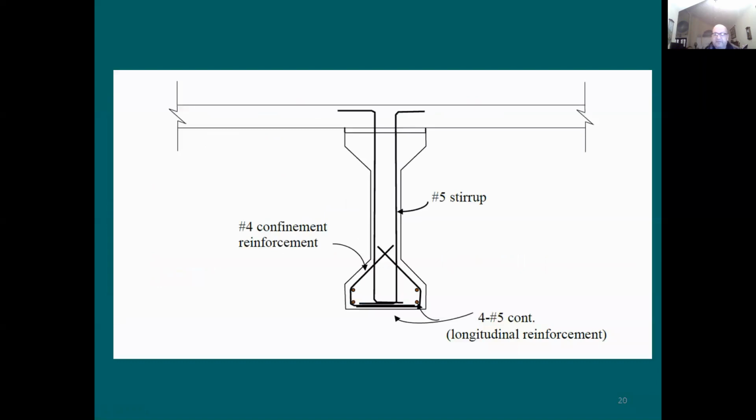In this picture here, it shows that you're going to provide number 5 stirrups. As I said, it's going to be either a closed stirrup or I can have a 90-degree hook. The reason that we have this 90-degree hook is to be sure that it's going to be anchored, because most likely you're going to see a rebar here and a rebar here. And once you anchor it, you're going to gain the tensile force or resistance that you wanted throughout this stirrup. If you don't have any anchorage, you cannot have any resistance for the splitting.